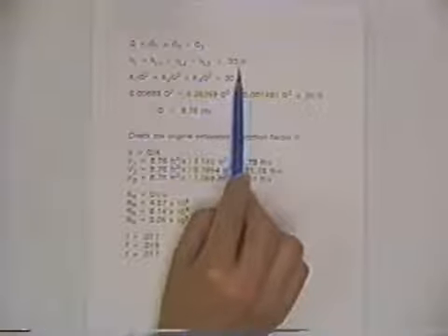We also recognize that the total head loss, which we know is the 30 feet difference in water surface elevations between the two reservoirs, is equal to the sum of the head losses in the three pipes. For each pipe we could write out the Darcy-Weisbach equation, but for convenience we're just saying K times Q squared. So head loss in pipe 1 is K1 Q squared, head loss in pipe 2 is K2 Q squared, and the Q's are the same. Then K3 Q squared for the head loss in the third pipe. All those head losses sum up to 30 feet.